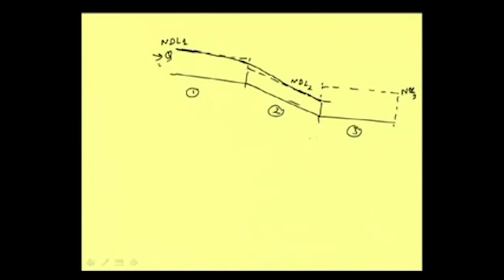Okay. Let me just talk about this part, because to know further detail will require some knowledge of this supercritical subcritical combination, and that we will be discussing later. But when the change in channel slope is there, this flow depth is changing. Here also the depth is uniform flow depth, and then it is changing gradually in this part, y1, y2, y3, and here it is uniform flow, say yn.